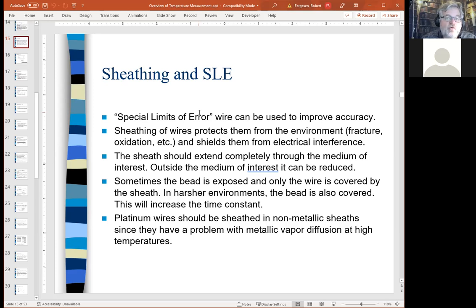If you short out your thermocouples even the slightest bit, even have it resting near some other sort of grounding source, you will not get an accurate measurement at all. And plus, it's very sensitive to EMF. So if you have it running near a 120 volt, 240 volt line, sometimes that can be enough to screw up your measurements.